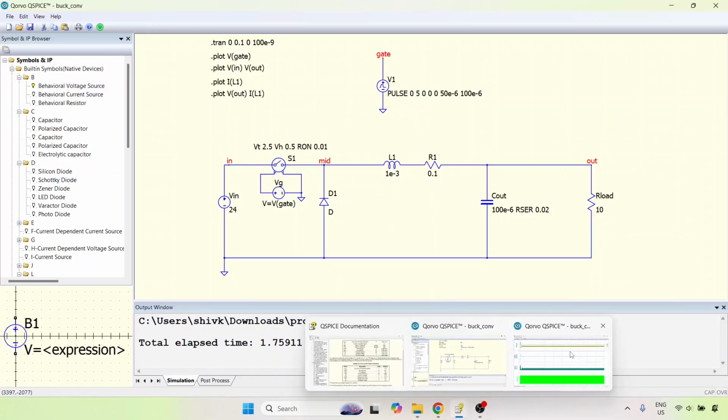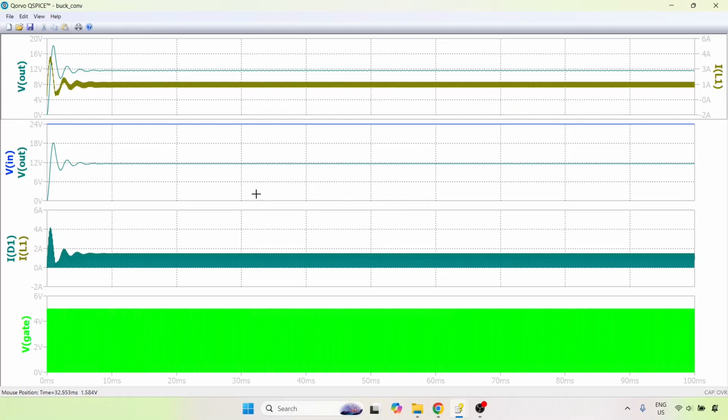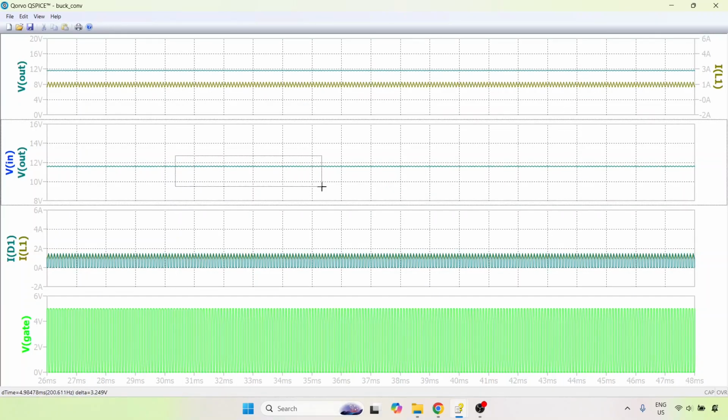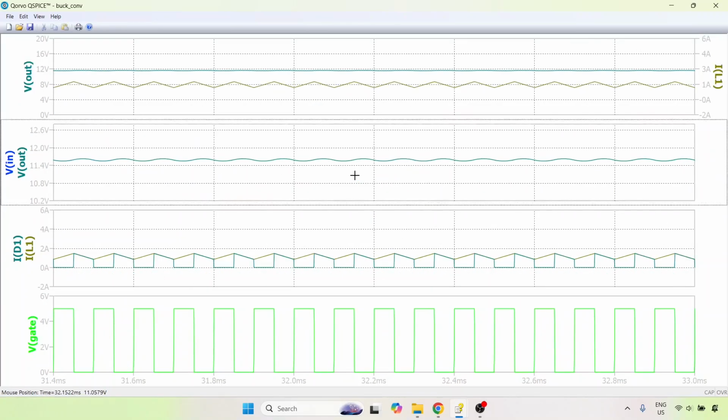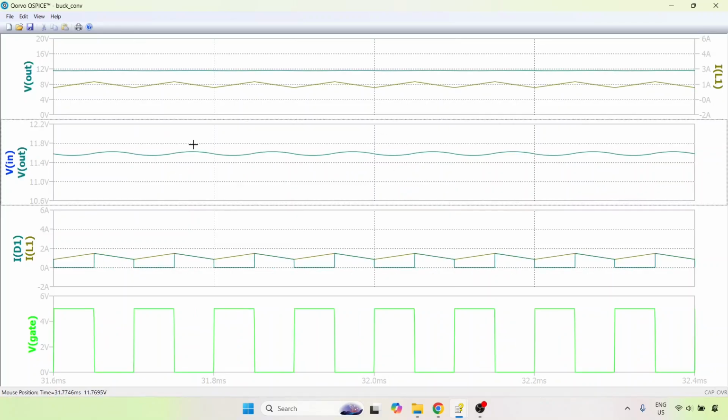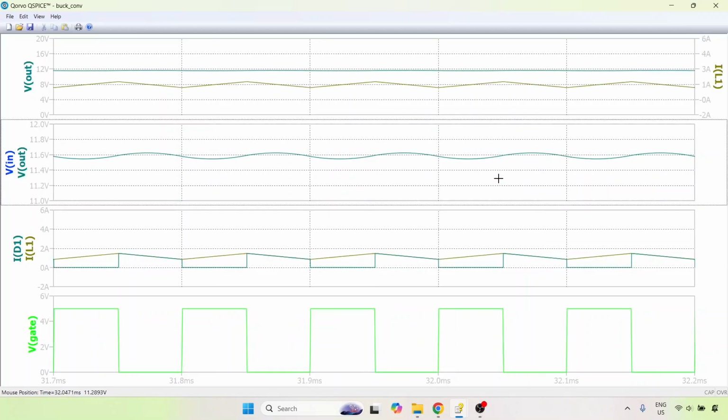And we should have got some result. Let's come over here. And now let's take a look. So let me zoom into the output voltage. And you can automatically see the result. You see now it is 11.5 volts, right? It is almost 11.5 to 11.6 volts. So you see now there is only a 0.4 volt drop from the required output voltage. And this is only expected.